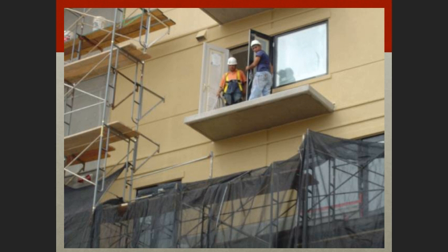These guys look very, very curious about why someone's taking a photograph of them, so that's kind of humorous there. But more to the point, I want to drive home a message here. So you see this individual wearing the orange shirt, and you can obviously see that he is wearing a fall protection full body harness, yet is not tied off. And so to the left we see some scaffolding there, and we see that there's a lot of things to fall on, and we have no means of protection.